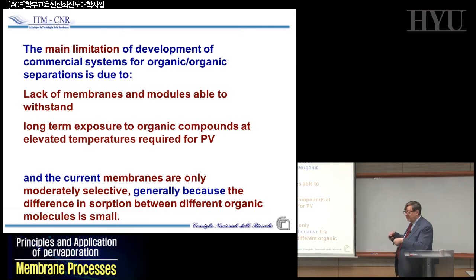So the module, how to put the membrane, the spacer you are using, how to promote turbulence, how to promote backflushing, how to promote high Reynolds number on the membrane surface, which are the parameters you can use for controlling concentration profile and fouling phenomena, are as important as the membrane itself. Otherwise, what goes across can be exactly what you're putting in. So that is quite important, and there is not yet a lot of understanding and industrial production in this area.